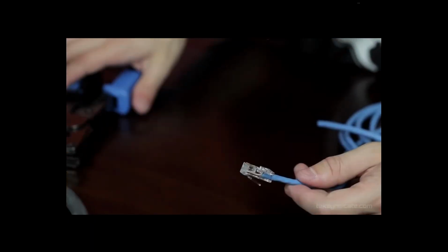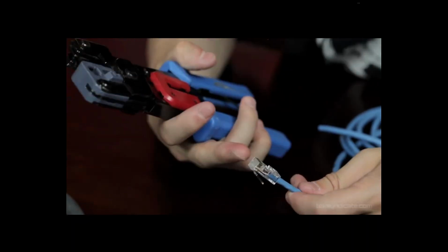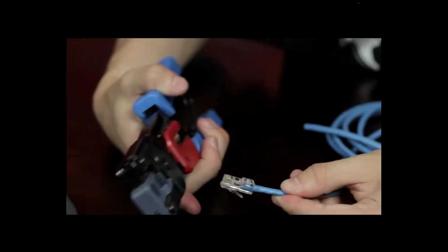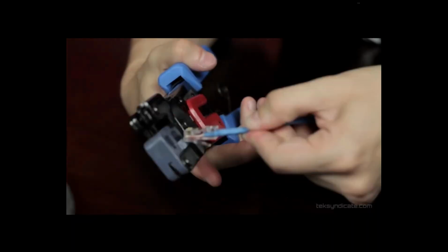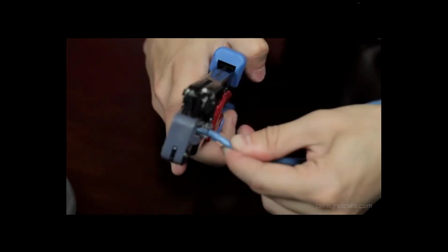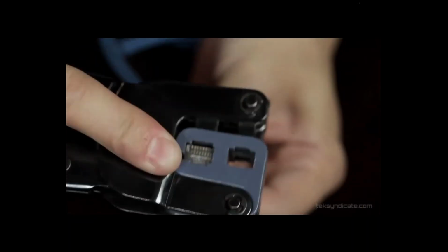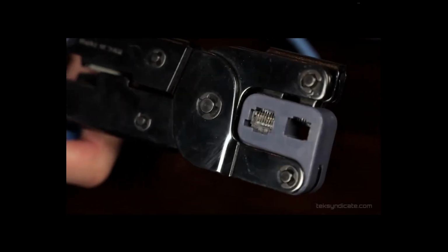Okay, so now we're going to go ahead and crimp the cable down. You want to make sure that you don't wiggle this too much once it's in place, and you're going to slot the mod plug into the RJ45 connector on the crimping tool. Again, check the other side of the cable. Make sure you see all the copper conductors. And I usually do this 2 or 3 times.